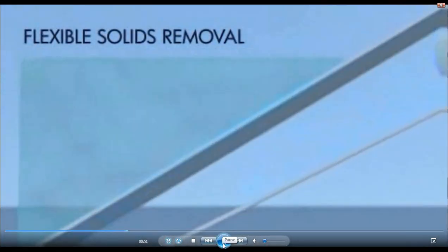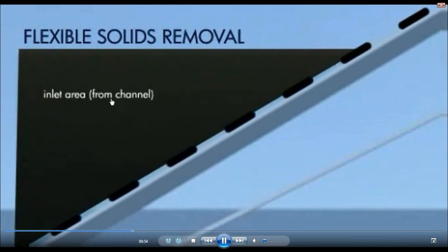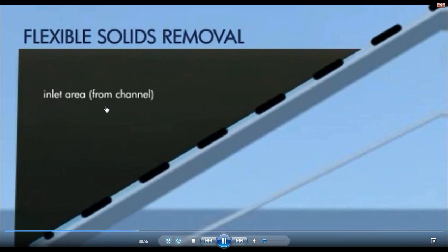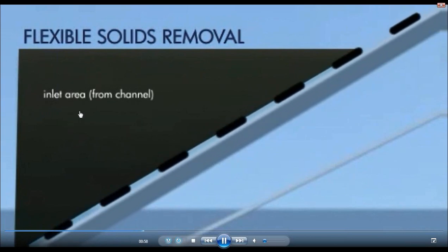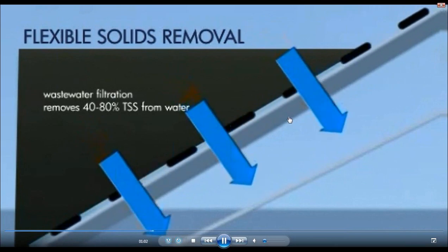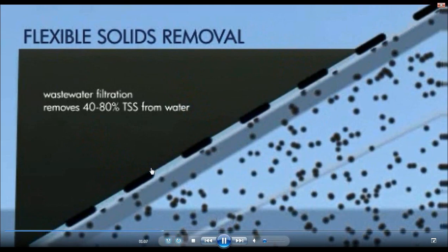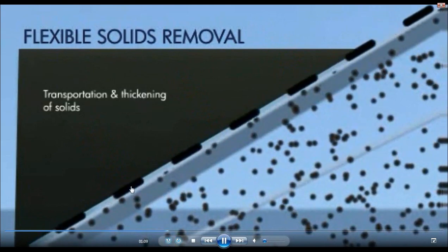But within the can, there's a cartridge, and with this video excerpt, you can see there's a tail roll and a head roll, and there's a drive motor off that head roll. There's dirty water, stormwater, sewage coming in the influent area of the channel, and this is level controlled. So that'll drive the VFD of the drive motor. The belt speed, there's a continuous loop mesh mounted on this cartridge, and this belt speed is variable.